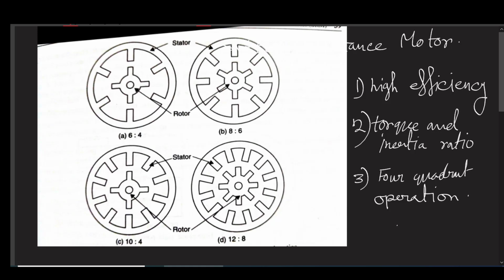Now, the stator of this switched reluctance motor is built up by stacking suitably punched silicon laminations to the appropriate length, and the stator has salient poles. These poles carry concentric windings, and here one thing we must not forget: the coils of opposite stator poles are connected in series, right? And this connection should be made very short.